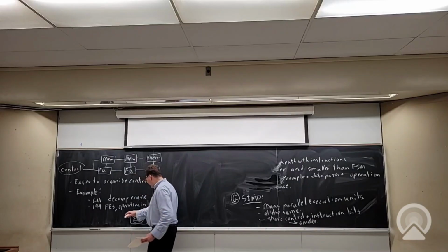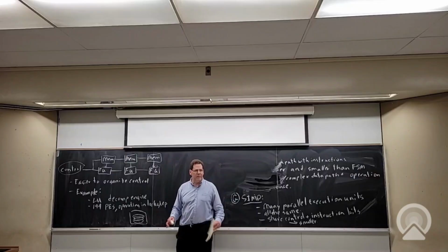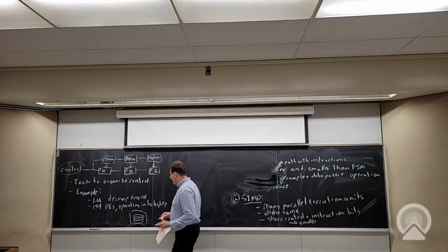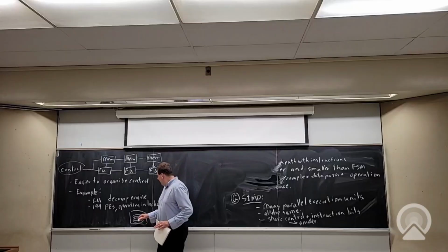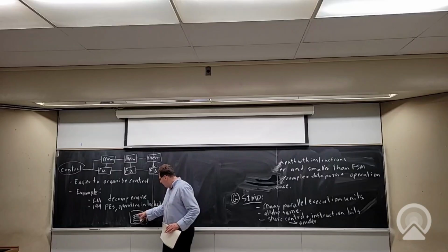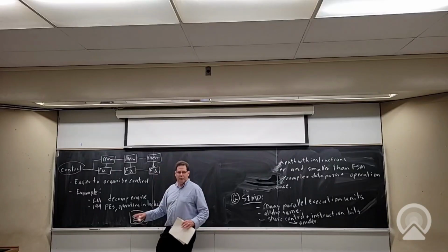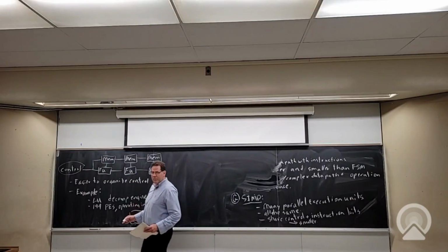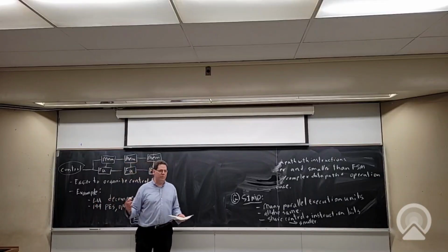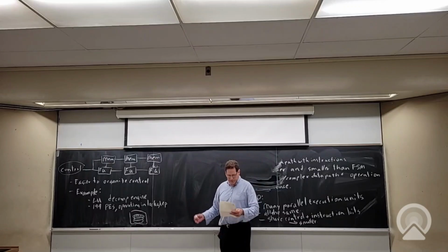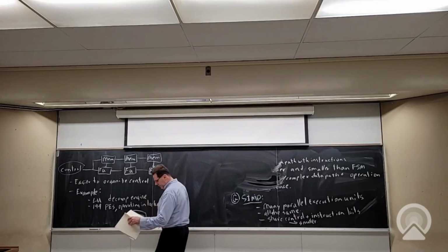Okay, so his control logic had to walk through this matrix, and it's a little more complicated than I've shown you here. It needs to walk through kind of in blocks and eliminate things from the right rows. But the fact that there's all this parallelism, in the end, once he figures out what to do for a certain row, it's a lot of vector subtractions from the rows below it. It maps very well to SIMD. So it makes it more efficient, also made it easier for him to think about, because he could see now the control was kind of simpler. So that was a good example of building a SIMD architecture.